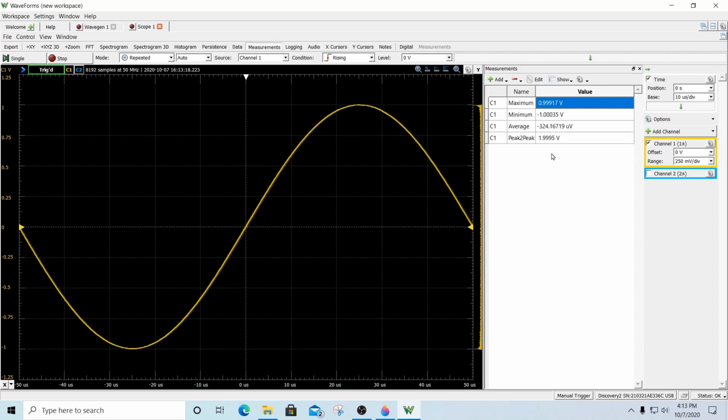And as you can see, it's constantly changing values because we're continuously sampling data from our oscilloscope tool. Now, if we wanted to get stable values, we would just do one single run. And as you can see, with a single run, it gathers a set of data, or data acquisition, from the signal. So we will get different values every time we click single run.